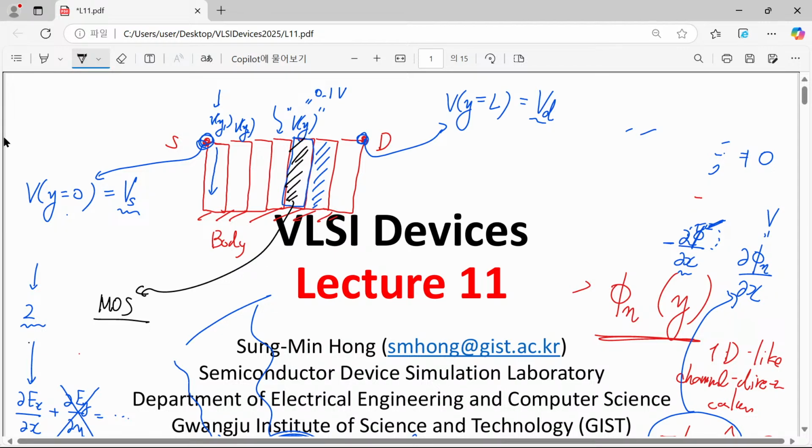In general, we have to consider the communication of the electric field between this central slab and the left slab and right slab. But we neglected that electric field component. What was the approximation? That was actually the gradual channel approximation. By considering the gradual channel approximation, we just neglect this electric field component. So now we can just consider only one MOS capacitor independently.